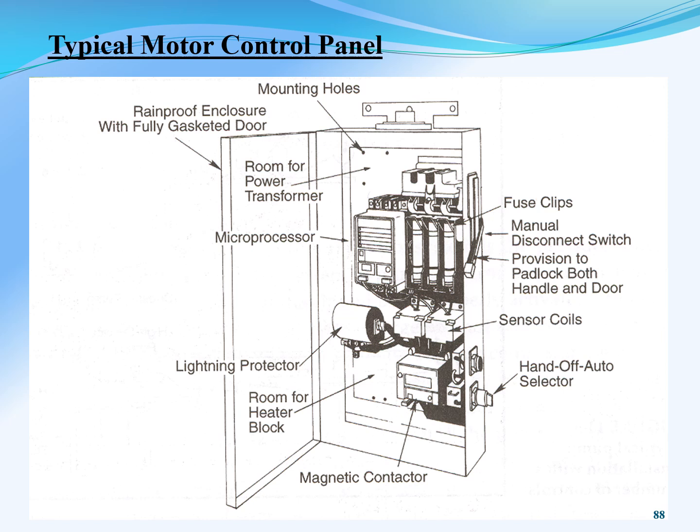So how do you control all your motors? Well, you have a motor control panel. Inside that panel, you're going to have fuses, sensors, your contactors, processors, some kind of a thermometer, and it's going to be fully enclosed in this enclosure. It'll have the HOA switch. It's all contained in this one spot for each motor. So each motor should have its own motor control panel.